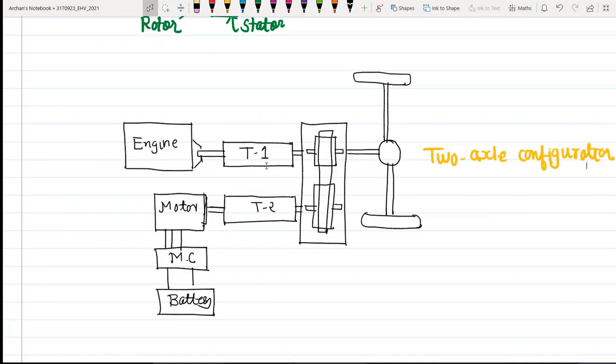So here it is clear that these two multi-gear transmissions will produce many tractive effort profiles. Okay, so the performance and overall efficiency of the drivetrain may be superior to other designs because the two multi-gear transmissions provide more opportunities for both the engine and electric traction system to operate in their optimum region.